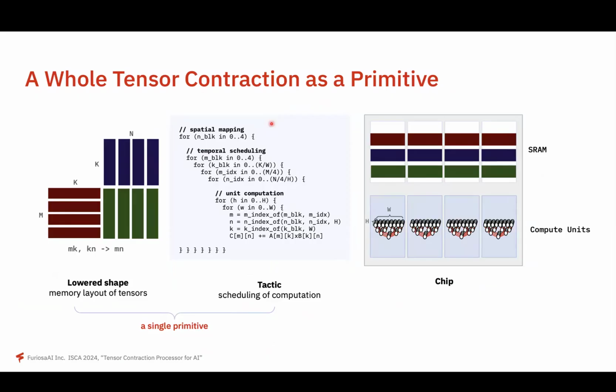But the systolic array is quite useful in matrix-matrix multiplication. In the case of generation by a large language model, for instance, it is mostly matrix vector multiplication. So the systolic array is not suitable for that kind of matrix vector multiplication dominated case.